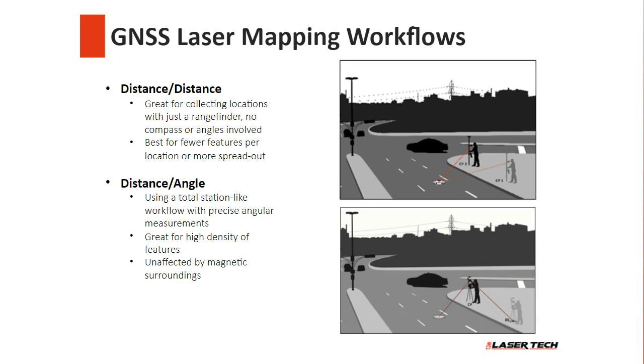And then we just turn our angle, and that's just a single shot, like the distance azimuth routine, to the object. And that within the software does create a distance and azimuth to use to calculate that remote coordinate. So another great way to get data in environments like this, and another super accurate way too. That angle encoder we have is really accurate, more accurate than the compass reading, so you can really keep your data tight.